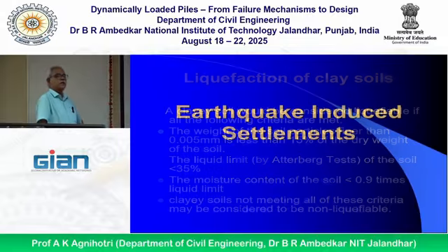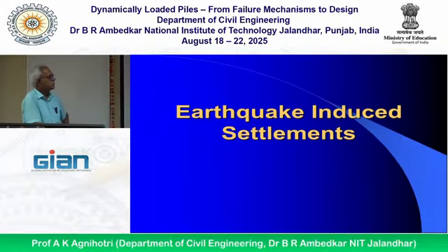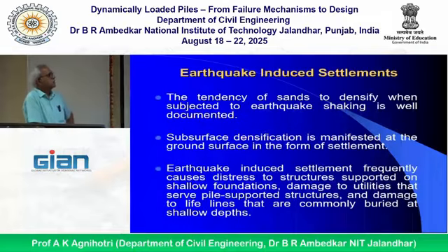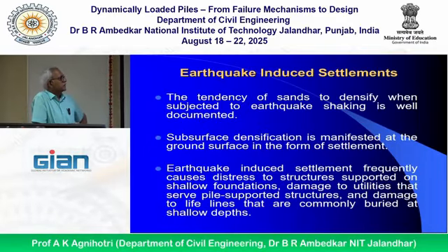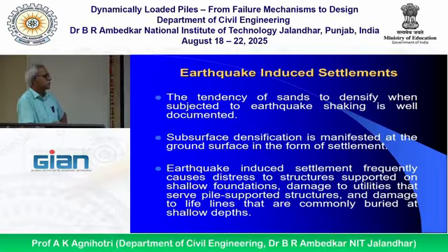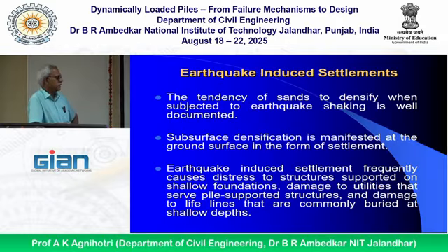Now we will talk about earthquake induced settlements. Tendency of sands to densify when subjected to earthquake shaking is well documented. Subsurface densification is manifested at the ground surface in the form of settlement. Earthquake-induced settlement frequently causes distress to structures supported on shallow foundations, damage to utilities that serve pile-supported structures, and damage to lifelines that are commonly buried at shallow depths.